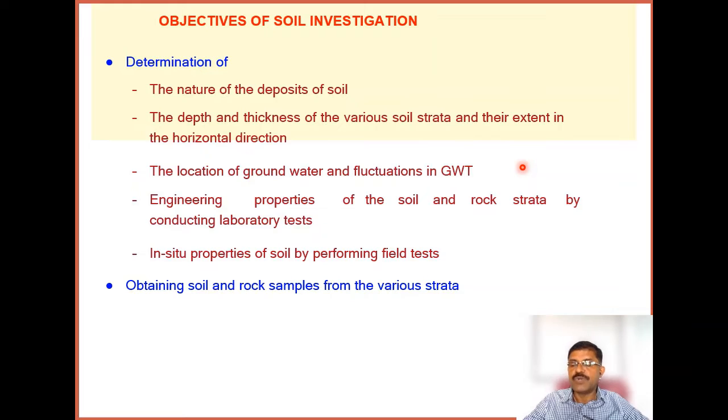I have mentioned to you about soil characterization, and in one of the previous videos you can check in my YouTube channel in the playlist. You can see the different methods adopted for finding out the engineering properties and other soil properties which will control the design parameters. Okay, so in situ soil properties are determined using field tests. This soil investigation also involves obtaining the soil and rock samples from the various strata for further studies.